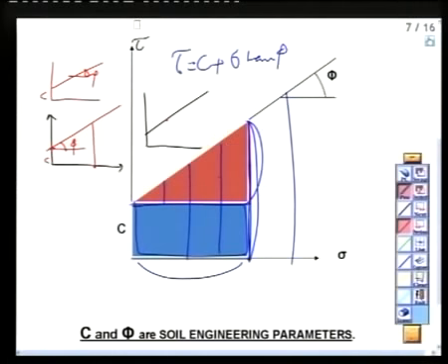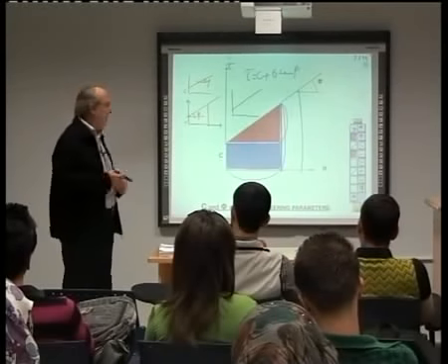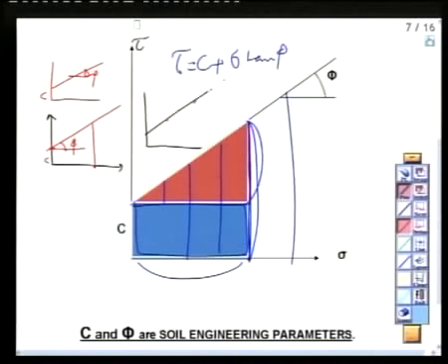I put loads on that sample. The sample was crushed, failed. So I counted how much load it was subjected to before crushing, and I put these points. These are the points that caused the failure, right? Now this gave me that the strength of the soil is 5 kilogram per centimeter square.